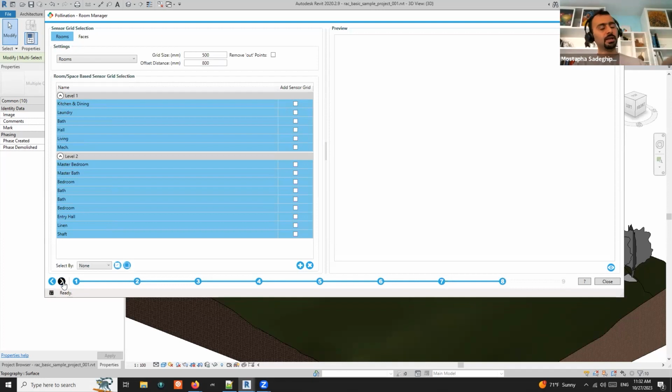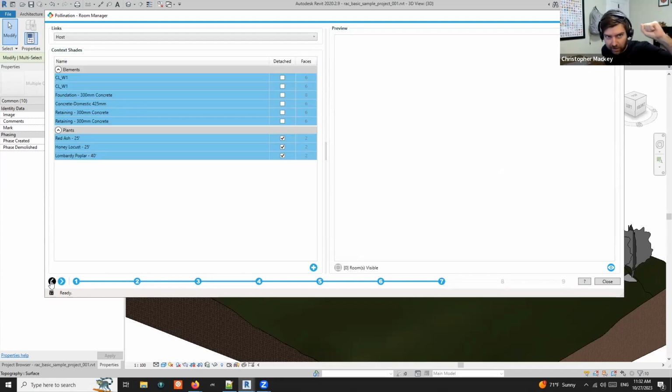Here is the place that you can add sensor grids if you want to run daylight studies. Mustafa, maybe I will just add that attached affects just the reflectance in EnergyPlus OpenStudio, the default reflectance. If you don't set it to anything else, context is 20% reflective, and building shade I think was 35. Okay, good to know. But yeah, continue. Thank you.